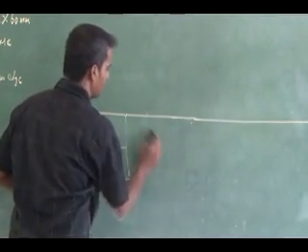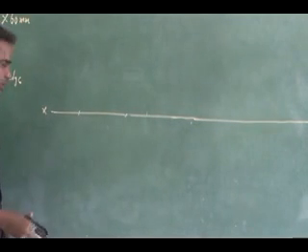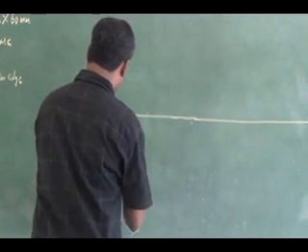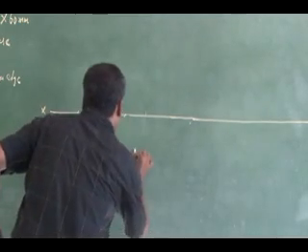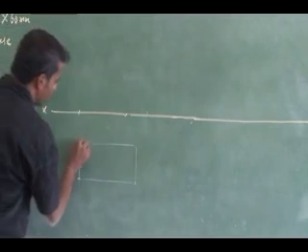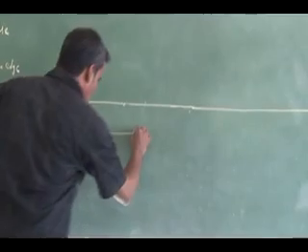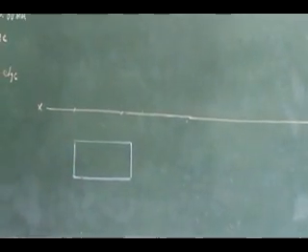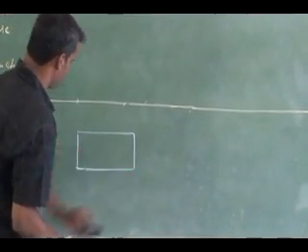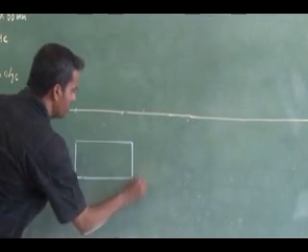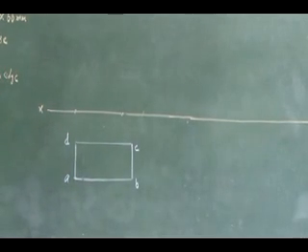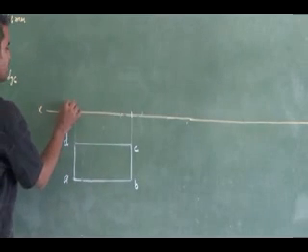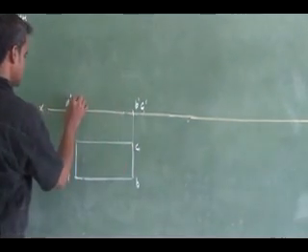So I have to draw my true shape in the first orientation that I have shown. This is 30 mm, this is 30 mm, and the length is 60 mm. So this is the true shape of the rectangle. Then you rotate it. From the left bottom corner you label A, B, C and D. So this is a top view. Now to project this in the first step, I will get my projections here: this is A dash, B dash, C dash and this is D dash.